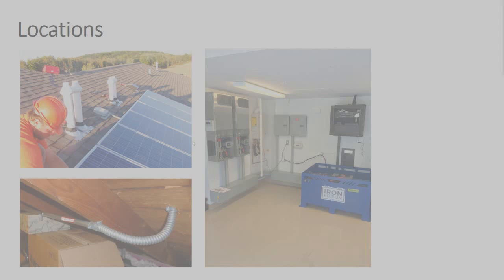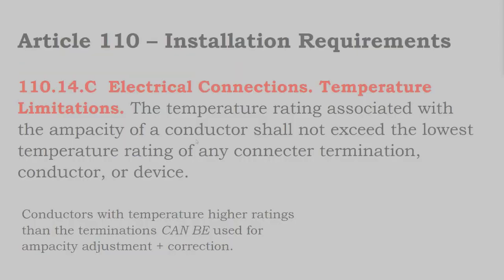And from that point, that's what drives your material selection. Okay, other installation requirements, connections. So the temperature rating associated with the ampacity of a conductor shall not exceed the temperature rating of any other connector, termination, conductor, or device. And what that means is